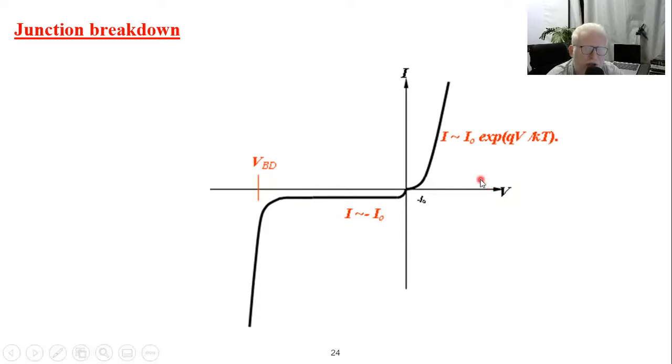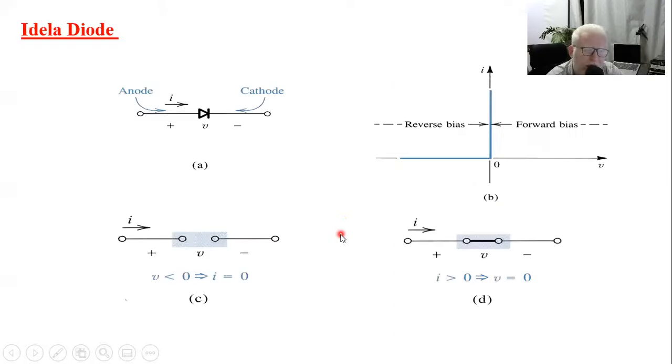where we approximated the IV curve of a p-n junction electrical diode into on-off states. In the on state, whenever the voltage is forward, the diode can be replaced by a short circuit, while in the off state, whenever the voltage is reversed, the diode can be replaced by an open circuit. Accordingly, we solved together a series of DC and AC circuits while treating our diodes as ideal diodes.